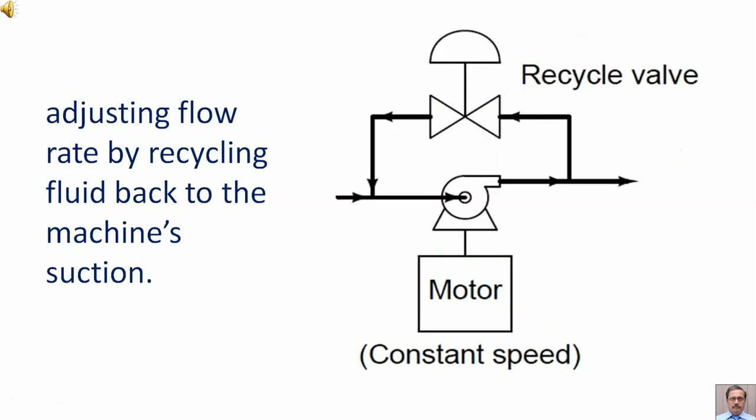Adjusting flow rate by recycling fluid back to the machine's suction. Here by opening or closing the recycle valve, one can decrease or increase the flow of fluid to the process.